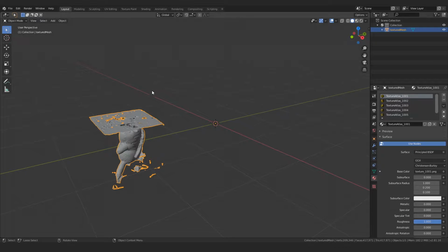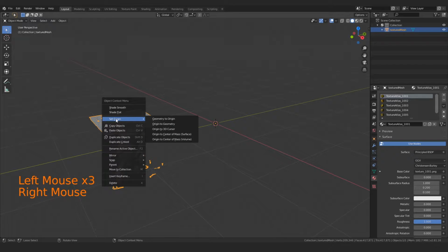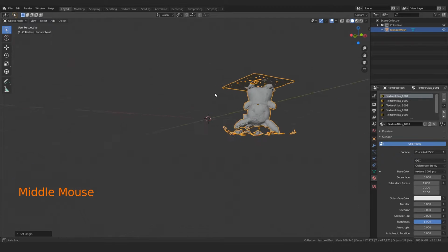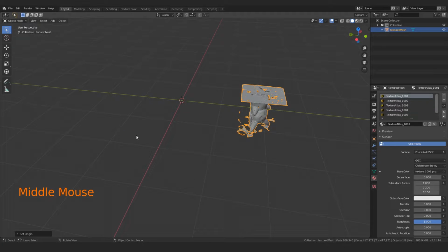So here what we want to do is selecting our object, however we choose to do that, make sure that this is selected, and I'm just going to right-click and say Set Origin, Origin to Geometry, and you'll see now that that orange little dot has jumped from the center of the world over to the center of the mass of our Pikachu. And if you have a mesh that has like an appendage that kind of goes off, it's asymmetrical, and it will try to jump this to the average center of all of the vertices, I believe. Like it'll basically approximate its center distance there. So this might not be completely centered if you have an asymmetrical model. Just keep that in mind. And there are a couple ways to work around that. I'll show you in a minute.